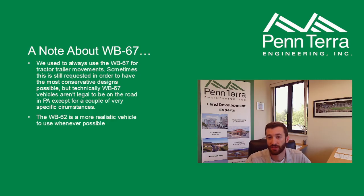So I threw this in here. We used to always use WB67s for our tractor trailer turning movements, and sometimes we're still required to do that, or it's still a good idea to at least try it to be conservative. But technically, a WB67 vehicle isn't legal to be on the road in Pennsylvania, except for some really specific circumstances that probably would not happen at our sites.